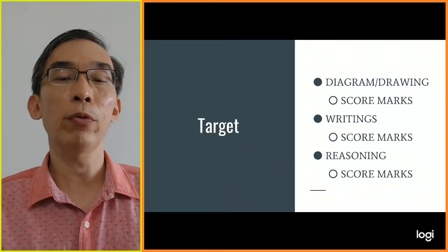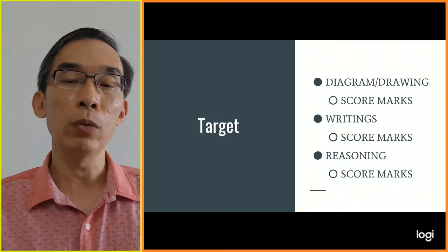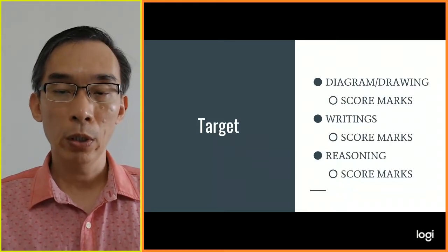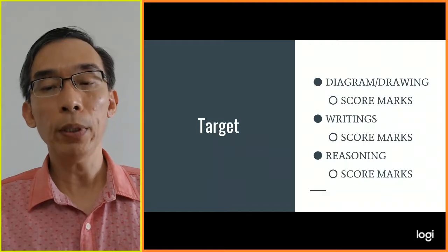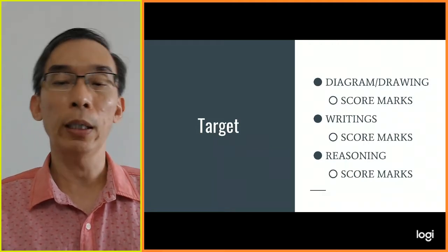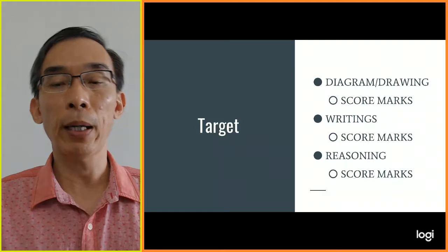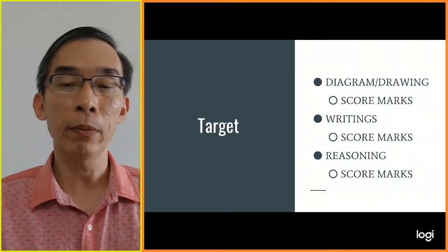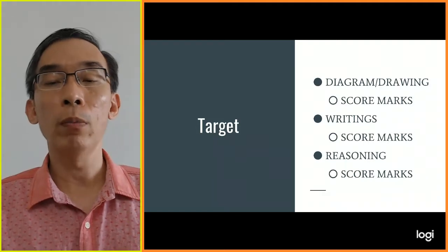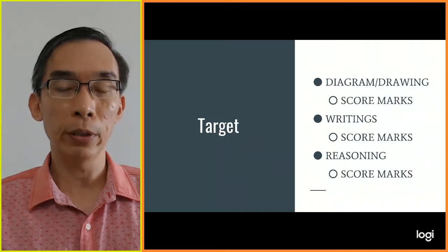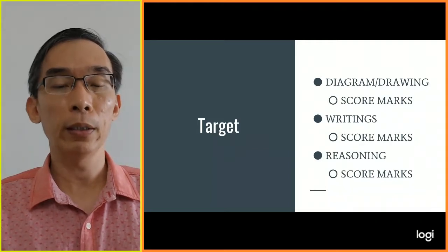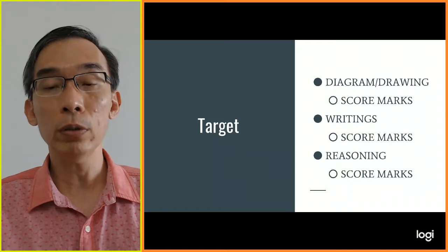Like say for example just now, why you choose a sliding window over an awning window. Then you have to give example lah. I choose to do this because there are passersby. I need to go to the garden. Sometimes all these protruding windows would have problems if I hit a danger. I get myself hurt. So these are reasons that you can give in the exam.